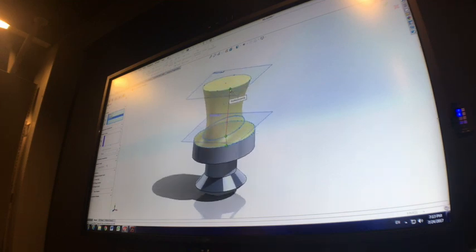These green points are control points, and they control the twist of the loft. Those control points come about from where you actually click on those lines. So clicking in random spots can sometimes cause issues. You might have something like this where you've selected all 3 but there's no preview.